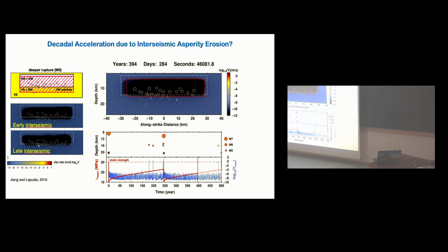So far, with the examples I showed you, this way of modeling the subduction zone seems to require that if you have fully locked patches, they're much smaller than the extent of earthquakes, and that I think might be ubiquitous. But there are so many other things that happen in plate boundaries, as we discussed: other earthquake cycle processes, other frictional physics, pore pressure changes that influence faults.